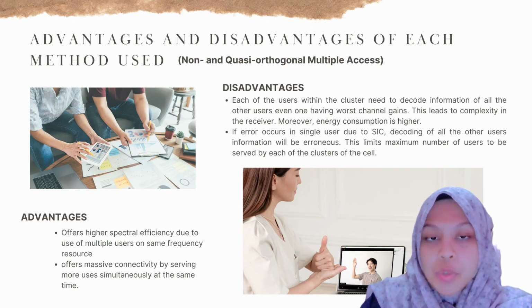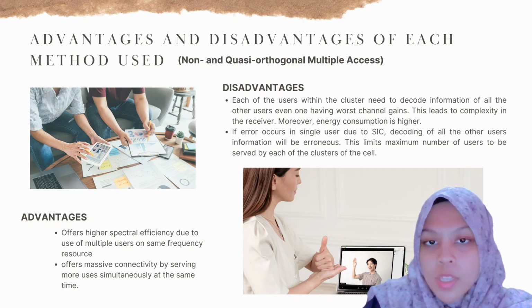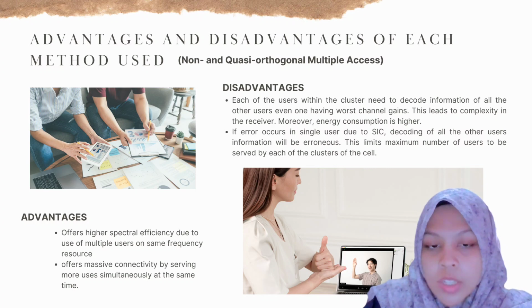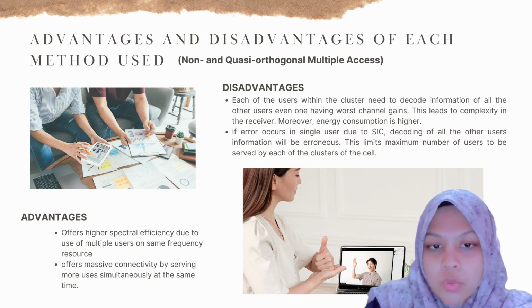So next will be the advantages and disadvantages of each method used. The first one is non-orthogonal multiple access, which is NOMA. The advantage of NOMA is it offers high spectral efficiency due to the use of multiple users on the same frequency. It also offers massive connectivity by serving more users simultaneously.